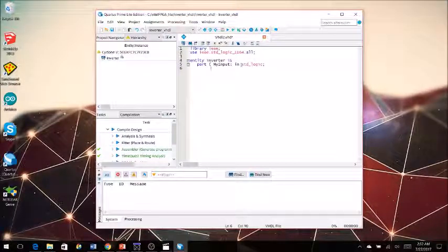And always remember semicolons. And now I'll do my output, colon, out, standard logic. Oops. Something important to note is we have to close this parentheses before we put the semicolon there. And then we'll go ahead and end it.